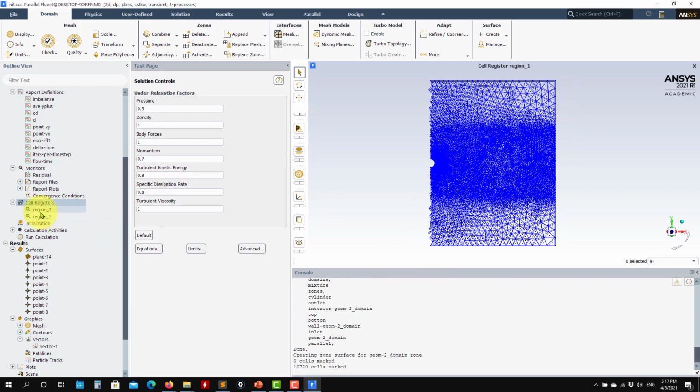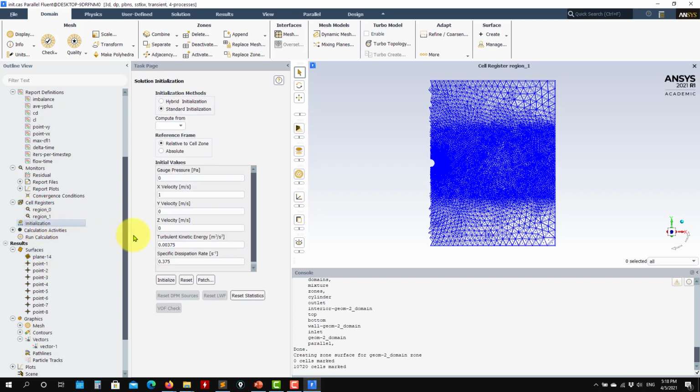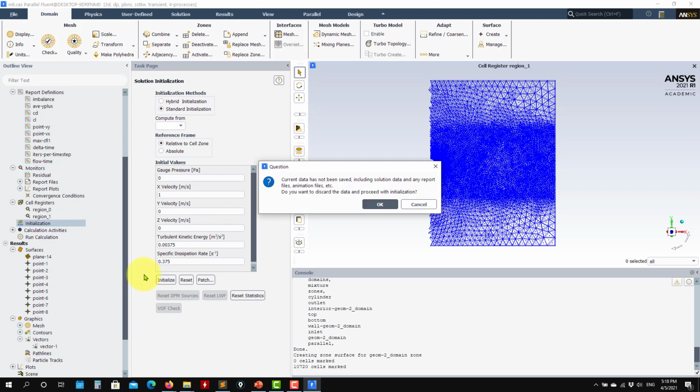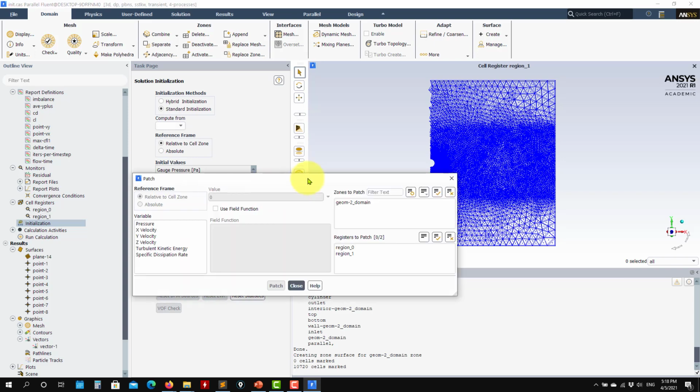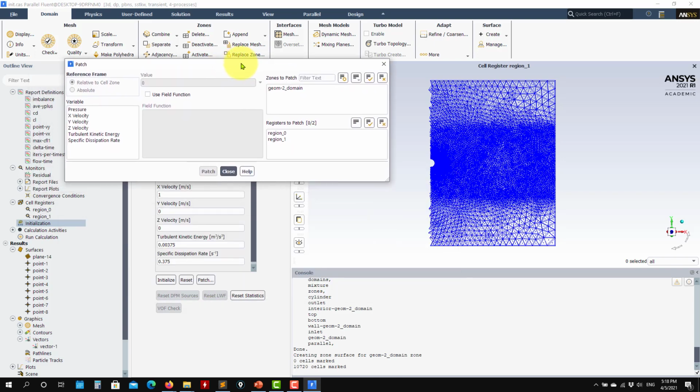So let me show you that you have the region here. So first, to do that one, you create your region, you select. So if you are going to work with multi-phase flows, this is something similar to initialize the free surface and everything. But here we're doing that to add a perturbation, okay? So then you go into initialization, and you use a uniform initialization, okay? Normal, but then see this box that you have here, patch.